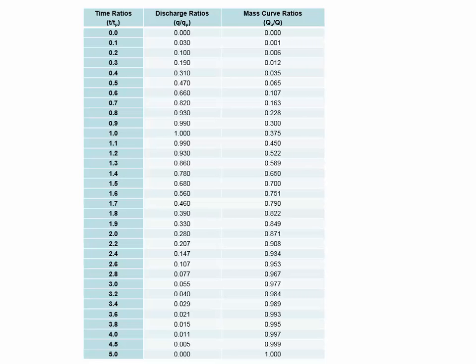From this table, here at 2 times the time to peak, you're only going to have 28% of the peak flow rate. If you go up to 1 at 1 times the time to peak, in other words, at the time of peak, you're going to have 100% of the discharge. But then it tapers down over time. So when WMS is generating hydrographs for you, this is the approach we're going to tell it to use. It has lots of different unit hydrograph methods and a lot of different time of concentration calculators. But we're going to use the SCS time of concentration and the SCS unit hydrograph.